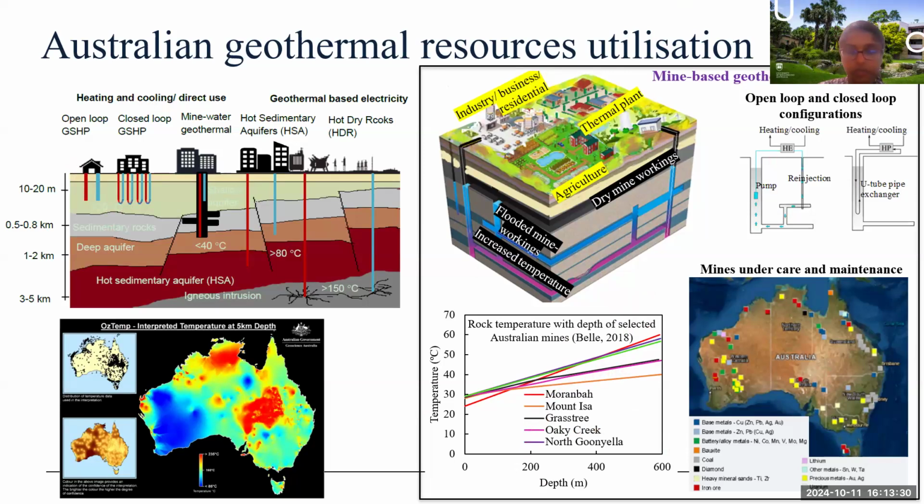And we also have a lot of historic legacy mines. The hydraulic conductivity of these systems is quite high when they are flooded because of artificial voids like mine galleries, shafts, fractured and porous rock, etc. Therefore, we can expect a very high water yield. And my current Australian Research Council project aims to identify these kinds of potential sites and discover various methodologies to make them usable.